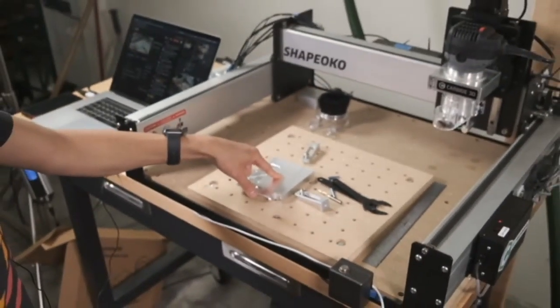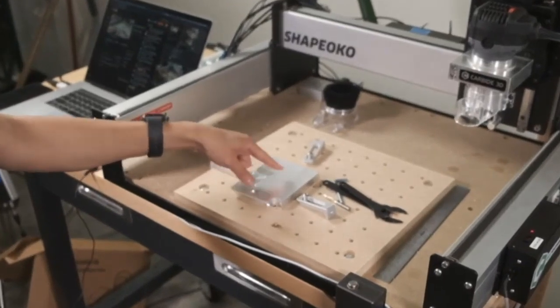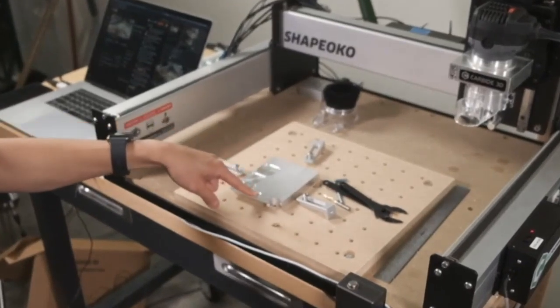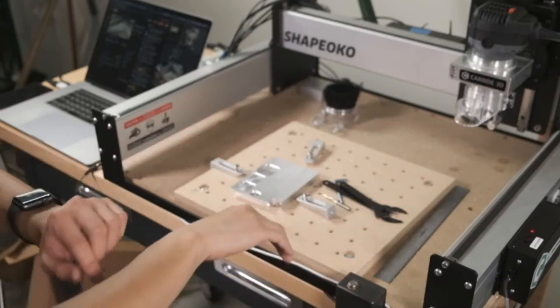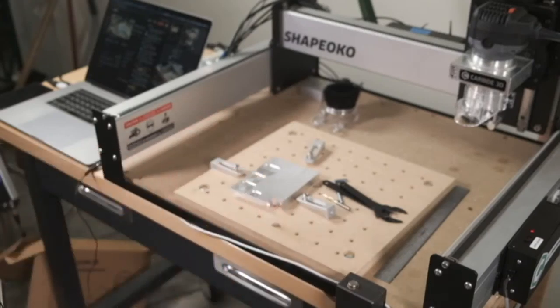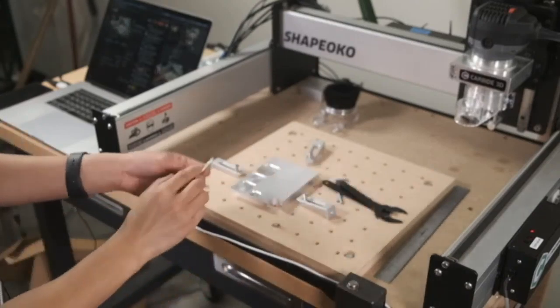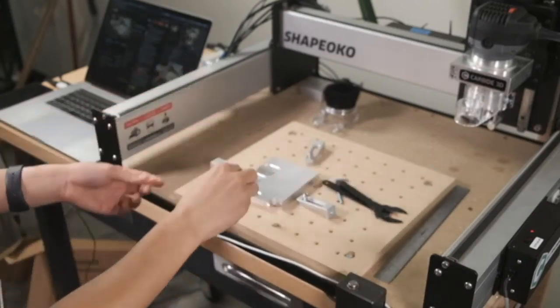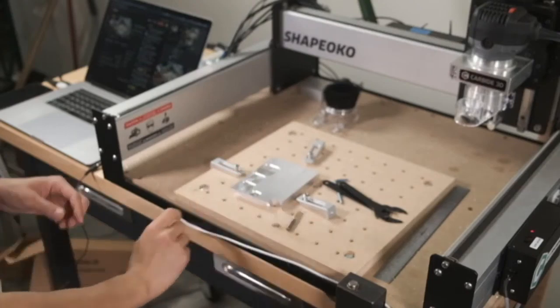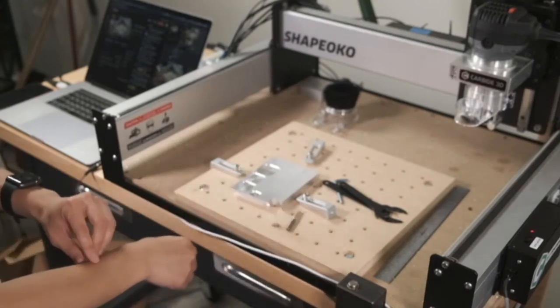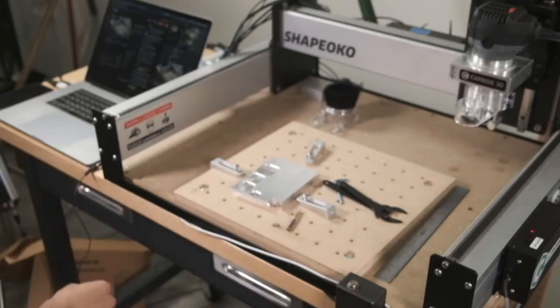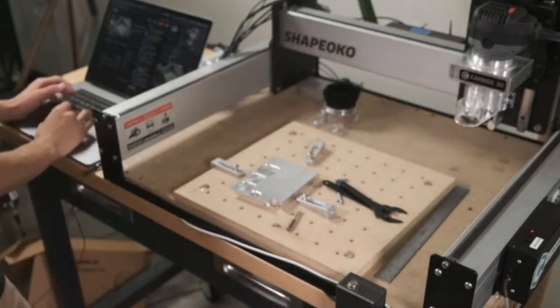The parameters were, I think, 46 inches per minute, 18,000 RPM. Depth of cut of 0.06 inches, so about 1.5 millimeters for you odd international folks. And an optimal load, so what fraction of the width of this tool into the material, it was 0.012 inches, so just over 1/4 millimeter.